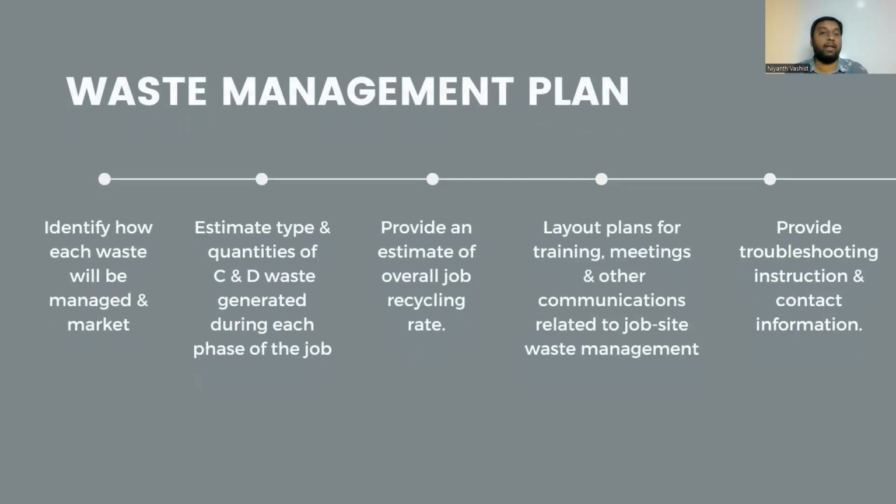Now let's understand the plan of waste management. The first thing is you need to identify how each waste will be tackled. Whenever you see a waste, let's say a demolition waste where you have a column, an RCC structure, and the whole column is demolished, you have the concrete and the reinforcement bars as well. Reinforcement bars will get into scrap, so it's very easy to recycle them. Concrete is where we need to think, okay, what can be done with the concrete. So identifying that is very important.